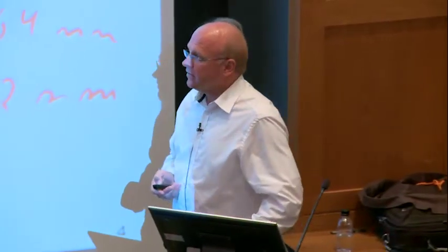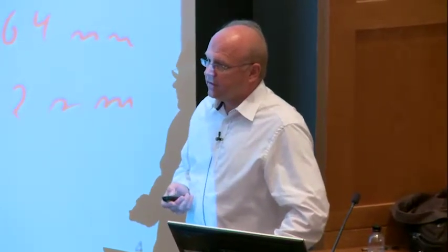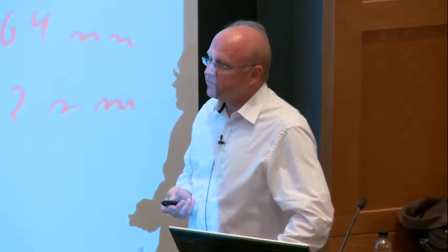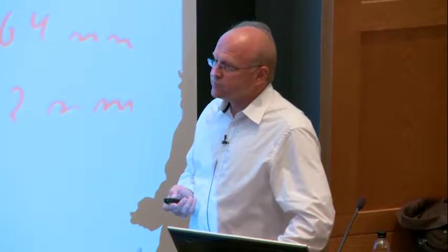If I'm taking a laser profile at my focal plane, trying to experimentally verify this R value, should I be using half width, half maximum? Yeah, what I do is 1 over e squared. The 1 over e would be 36%, and 1 over e squared is even smaller, and that is what I take as the beginning and the end of that profile.